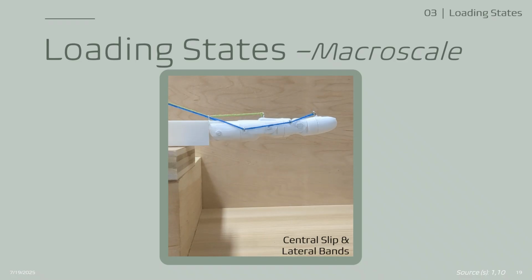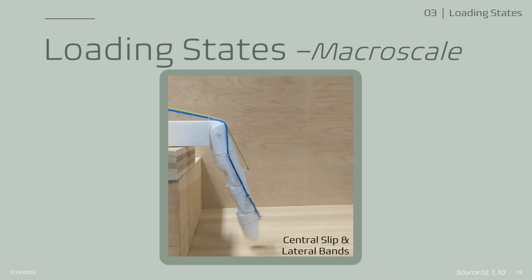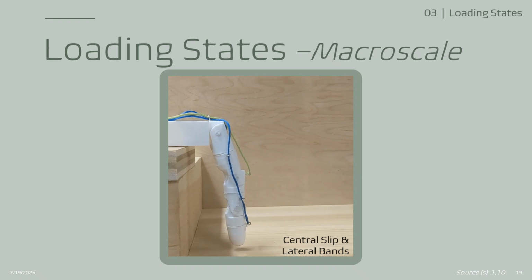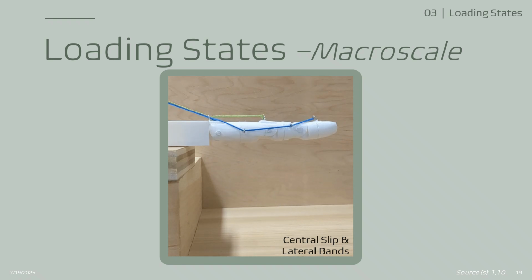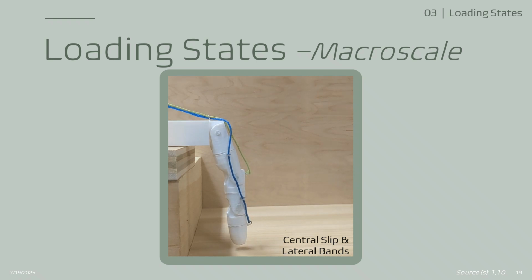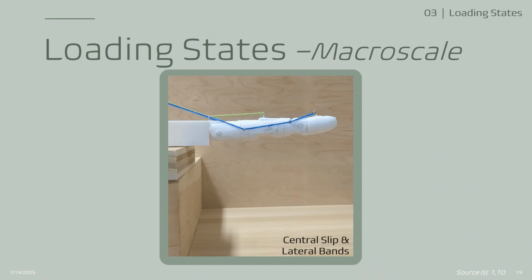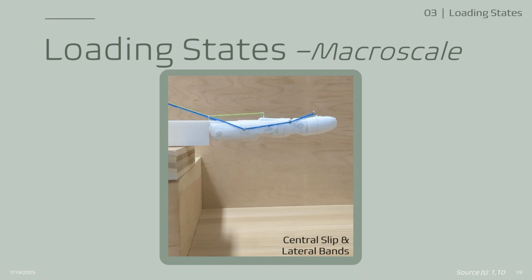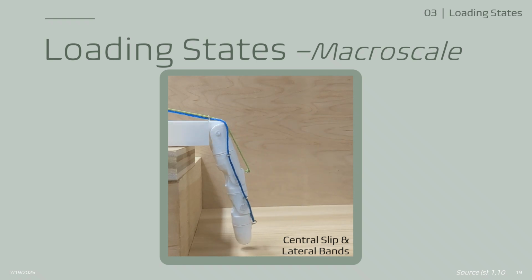To demonstrate how the tendon transmits force into the phalanges, I have made this model. This is a 3D model for the finger, and it was made by InMoov, which is an open source humanoid robot project. Inside the finger, there are 2 strings running palmar and dorsal to the finger. I tied both of these off in equal tension on both sides. I then attached loops to the EDC tendon attachment points on the phalanges and ligament attachment points. It's not a perfect model, but it is close enough for our purposes.